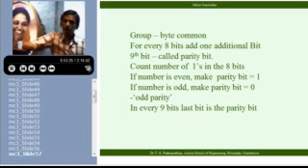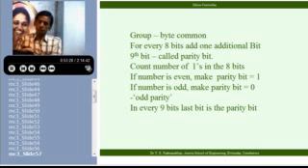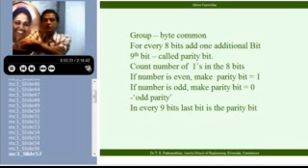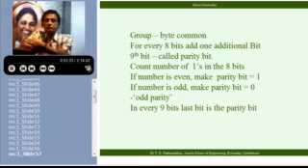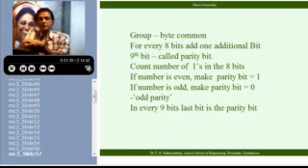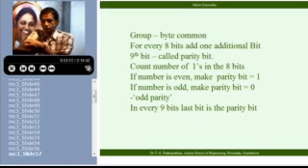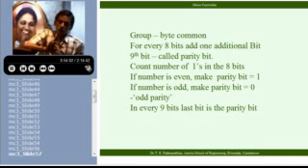Now, in the digital system, where you are using this parity bit for building redundancy, you should have a scheme by which this can be identified. For example, in a microcontroller-based system, there will be a transmitter and a receiver. The transmitter will add a parity bit and transmit the data. The receiver will get the 9 bits and check whether there's a parity error. After checking, it finds there's a parity error and discards the whole bit combination. Whenever a bit combination is discarded, that receiver microcontroller will make a noting. Look, there is an error. It will just blow the whistle once.